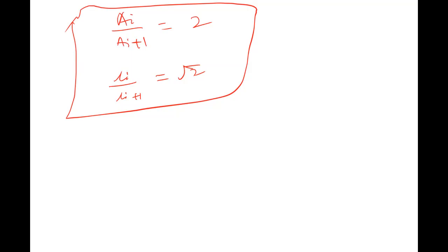Suppose I'm asking, for a particular mesh, its size is defined as minus 150 to plus 170, and I ask you to calculate dpi bar. What is the average size of the particle here?